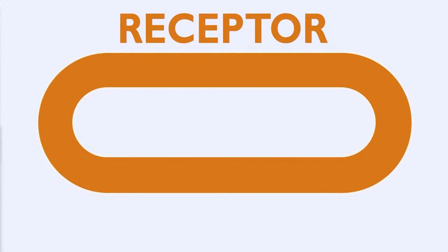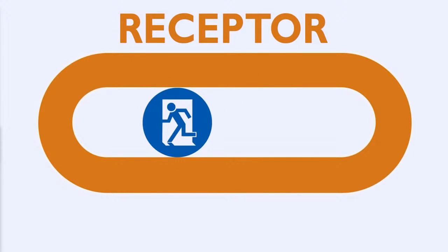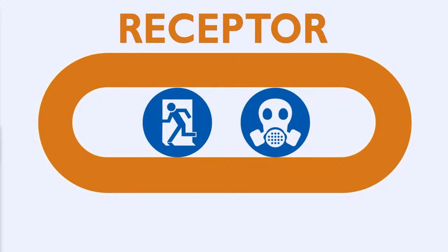Receptor. Receptor management is the most problematic of the three strategies, mainly as it can come into direct conflict with the purpose of the building or structure by placing restrictions on the occupants which may prove unacceptable. For this reason, receptor management is most commonly used only as a temporary measure, while a longer-term strategy is developed. For example, restricting access to buildings during decommissioning of an industrial site, or evacuating residential properties in response to a nearby chemical spillage. Another more common example of receptor management would be health and safety requirements placed on contractors during remedial works, such as PPE or safe working practices.